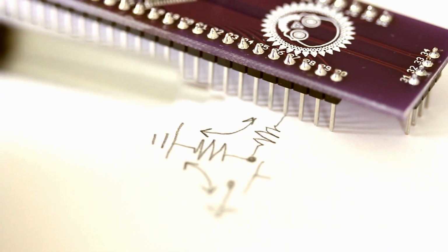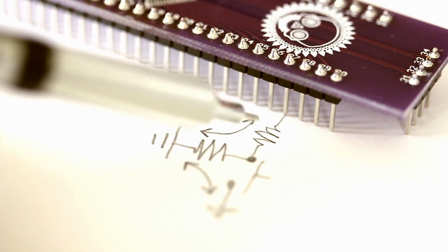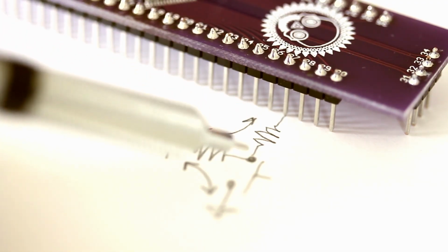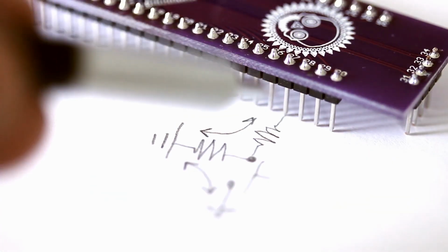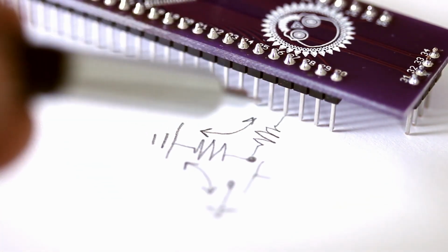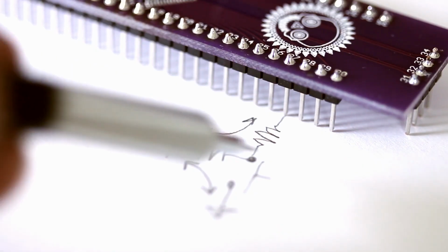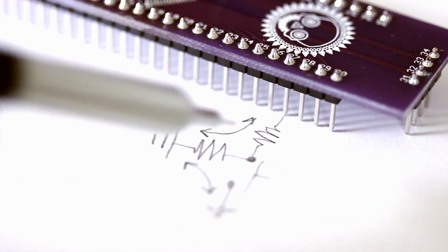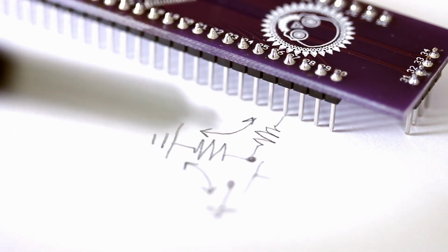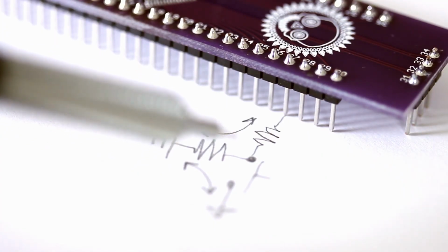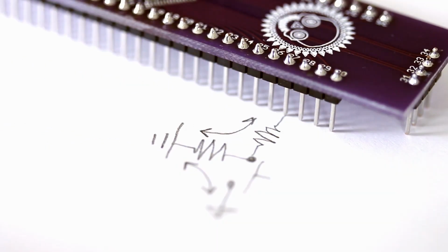If we didn't have a pull down resistor externally and we didn't have the pull up, pull down resolved internally, when the push button is not pressed, this would be in a floating state. And you'll notice quite unpredictable behavior. Even waving your hand over the circuit could cause unpredictable outcomes. So when you're putting a circuit together that has an input, that is the mode for the particular pin is set as input, you want to make sure that it's either pulled down or pulled up and not in a floating state, because that input is going to be acting like an antenna and can pick up noise. And if that noise goes above or below the thresholds for TTL circuits, transistor to transistor logic circuits, it will produce an outcome, make the LED turn on or do some other unpredictable effect if you have a much more complex circuit.